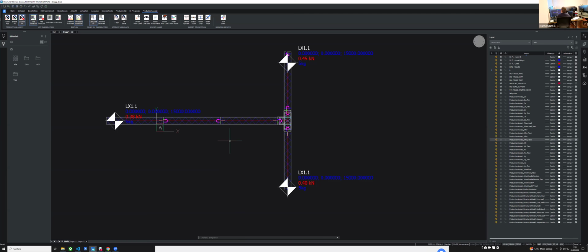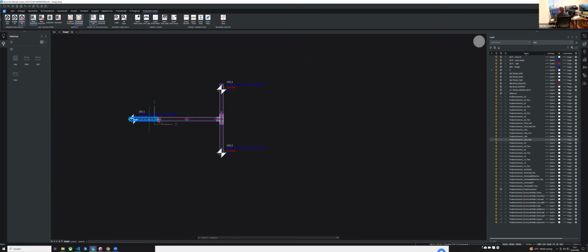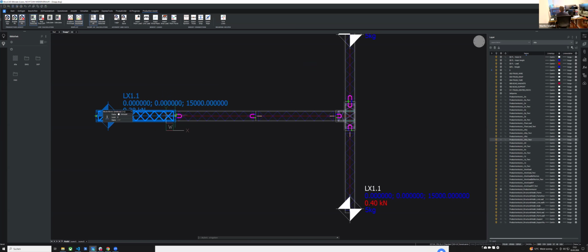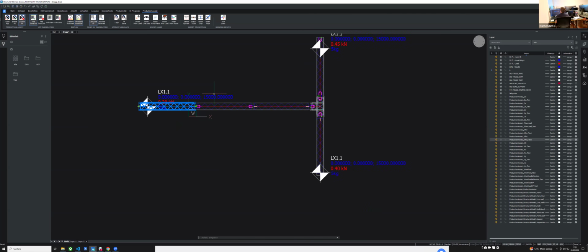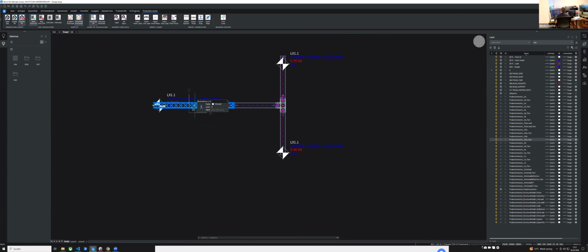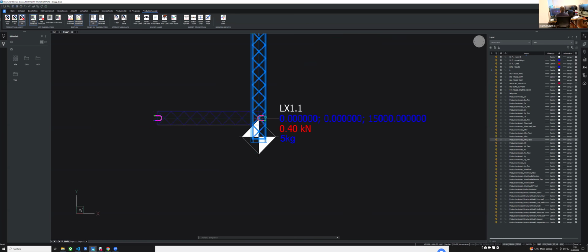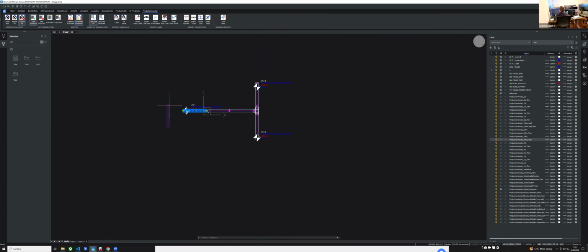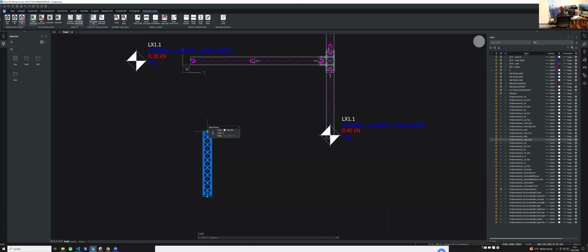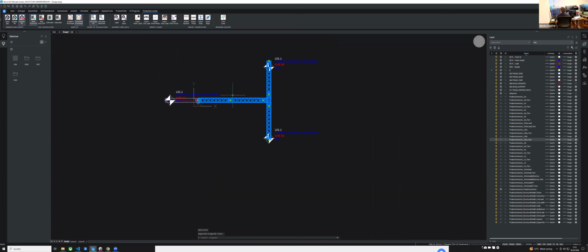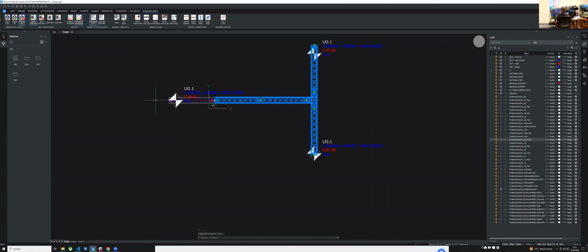One of the new functionalities that we have is when you select a block in here, you actually see that it now has two handles, these ones. With these handles, you can copy or you can move this. So if I'm using this in here and selecting it, it will automatically align to this and snap to this specific truss so that I can connect it with it. It's a really cool feature to move stuff around. If I want to move it back, I just can snap it and you see it automatically aligns and rotates this.